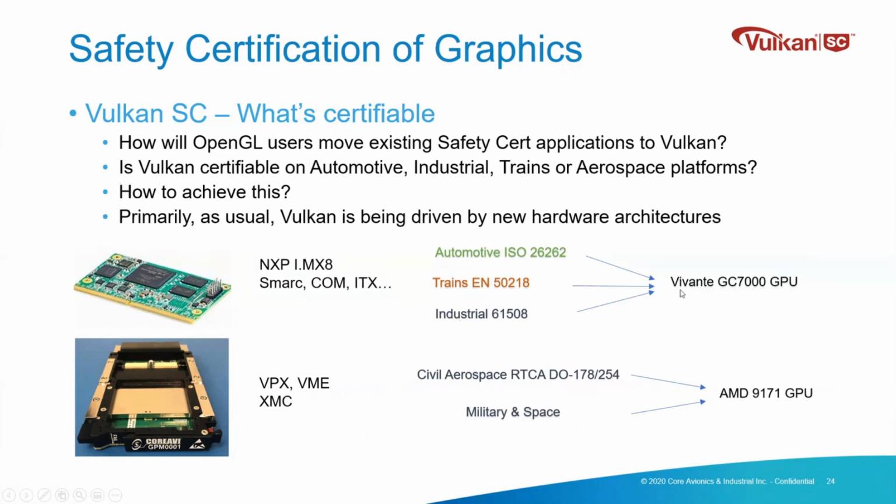So it has dual GPUs from Vivante that are safety certifiable up to the highest levels for these markets, as well as aerospace as well. We know a few customers using i.MX8 as well, certifying to DAL-A on aerospace projects. And the i.MX8 is a little bit different from the E9171 because the i.MX8 is very low power.